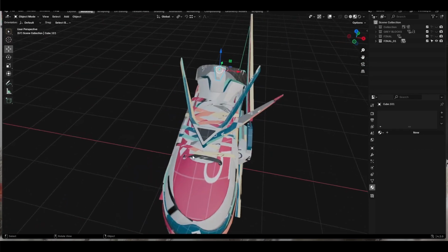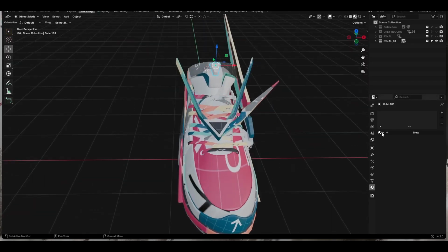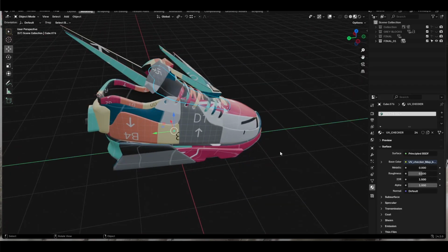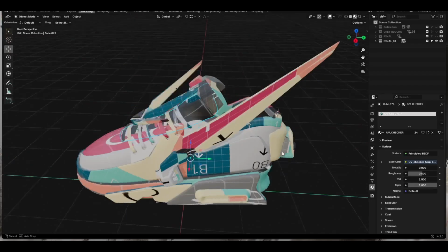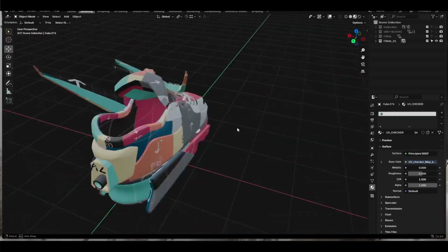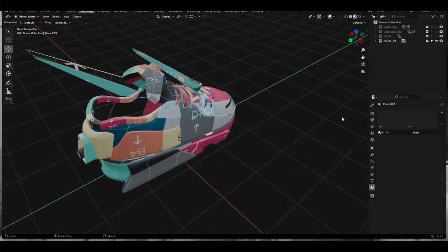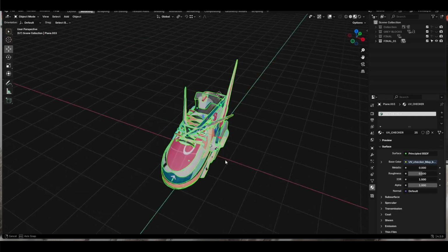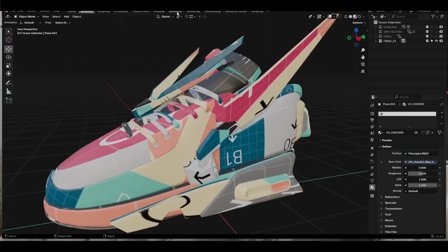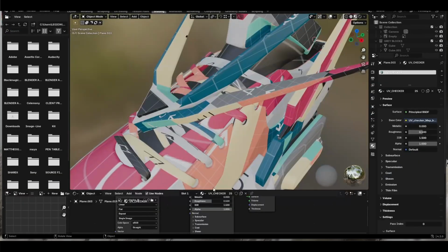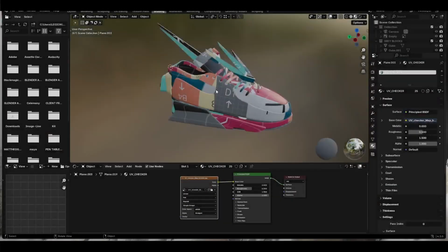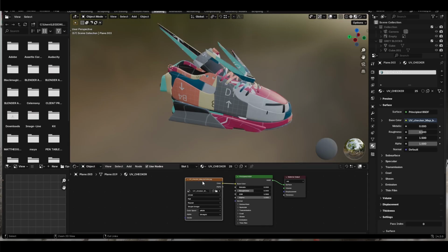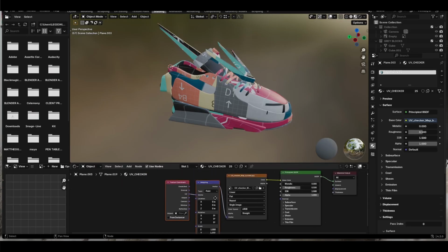As you can see, we already see stretched UVs upon checking. It's gonna be difficult to fix. Okay, I think we added this one. Let's double check. Okay, everything was already added. So next, we go back to shading. So we need to click this one and hit Control T. It will automatically add a texture coordinate.